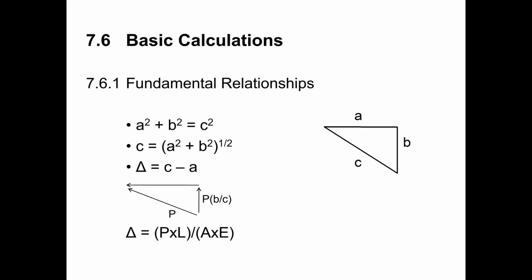So generally a bed has to be reinforced underneath to resist the load, that vertical force that results from hold down locations. And then at our hold up devices, whether we're using a column or we're using a portal frame as our hold up device, that assembly has to be capable of resisting that vertical load that is generated at that hold up location. So that's one of the things that we're going to calculate. One of the 2 things that we're going to calculate in Chapter 7 is what is that vertical force at the hold up and the hold down location.